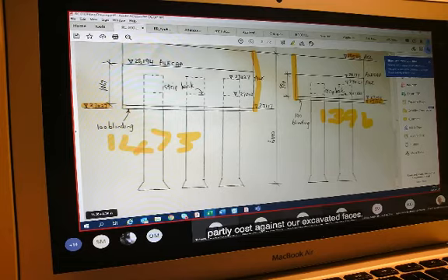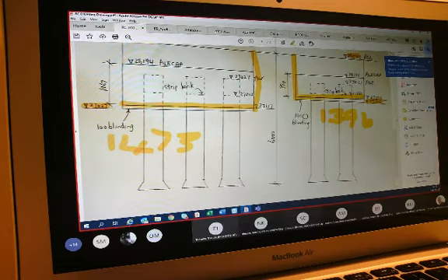With that, I'll then also have to do my concrete. My 30 MPa 19 millimeter stone reinforced concrete in pile caps, partly cast against our excavated faces. Why partly cast? Because part of that is cast on top of my blinding that you see there. Therefore, I'll be using the same dimensions that I had for my blinding. So 3.51 by 0.91 by 1.07. Alright, where do I get this 1.07 from?